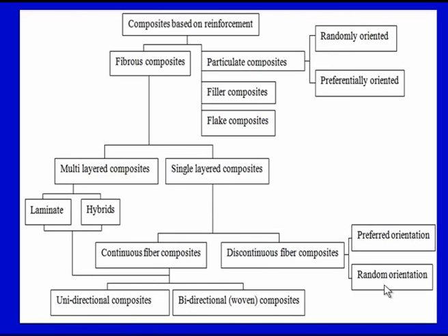All the fibers in one direction, suppose the tensile strength in that particular direction would be very high, whereas the tensile strength transverse to the direction of fibers would be comparatively low, because the fibers are the main load bearing members, which we have already seen in our previous lectures. So when we are loading a particular composite which is having all the fibers in one particular direction and we are using long continuous fibers as the reinforcement in a polymer matrix, the load when applied in the direction of the fibers, the failure load would be very high.